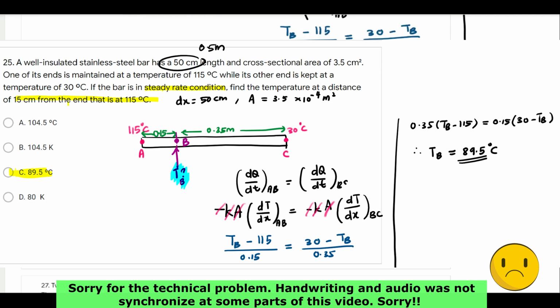So determine at what temperature the rods will just come into contact. The question states to determine at what temperature the rods will just come into contact. The coefficient of linear expansion for the brass and the copper is given. So let's start. I will write that for the brass, the equation of the change of the length is equal to alpha B L naught B delta T.